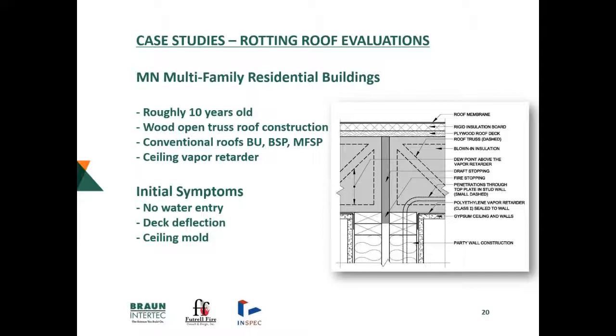But symptoms for these projects, not a lot going on as far as leakage, no water entry coming down from the roof. A little bit of ceiling mold was picked up on a couple of the projects inside at the interior walls, from interior to outside walls to ceiling. But the most interesting thing, the most telling thing was that there was deck deflection under foot traffic.